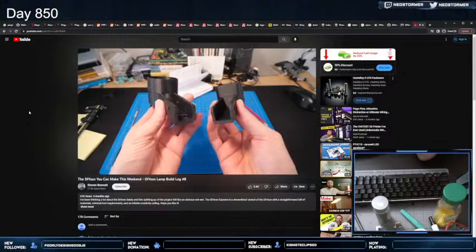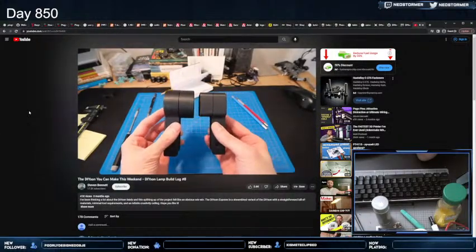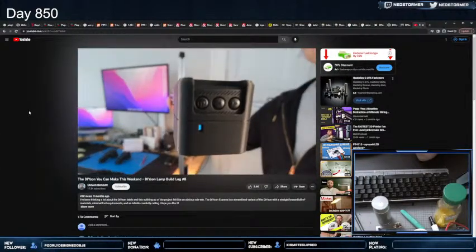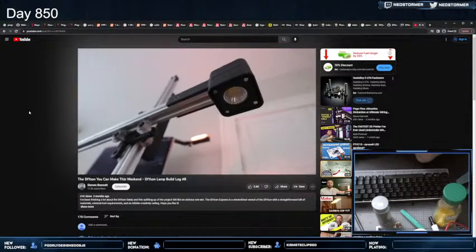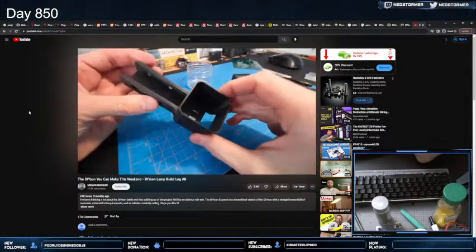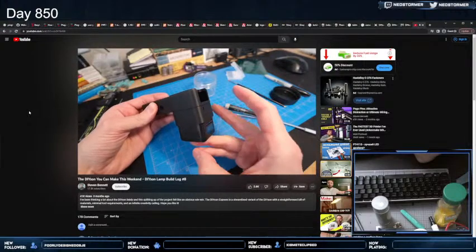Matching radii around the corners, a super thin shell, and a strategically placed part line give it a less monolithic look. And I even included a cute little window for the battery indicator to shine through. The design feature that makes all this work is the mounting solution. This LED cube has an embedded magnet, so by embedding my own magnets in the enclosure, the cube can be popped in and out of place effortlessly when it's time to charge.